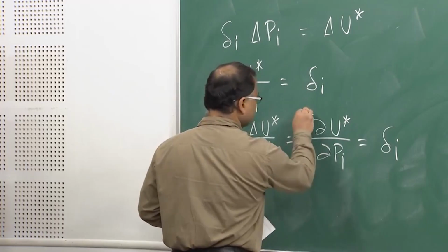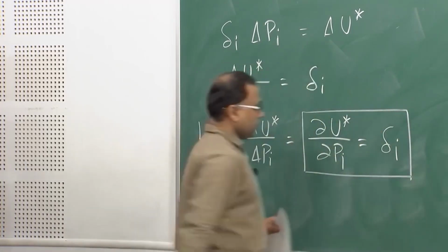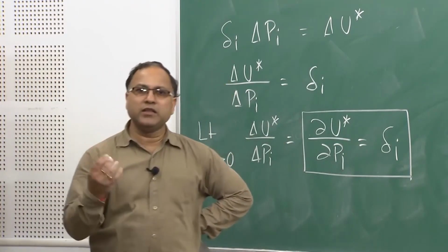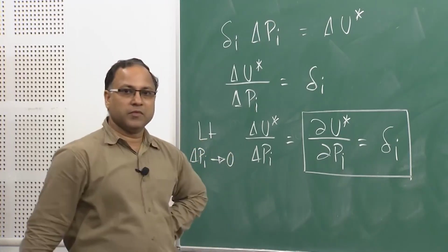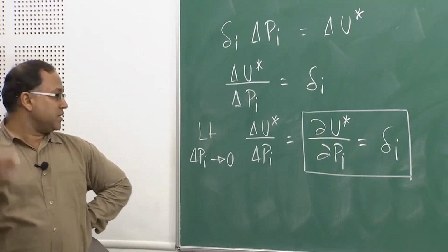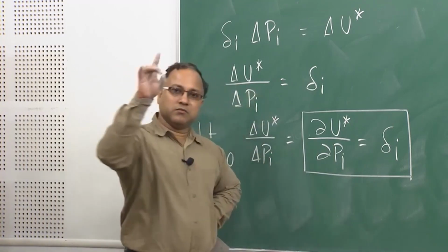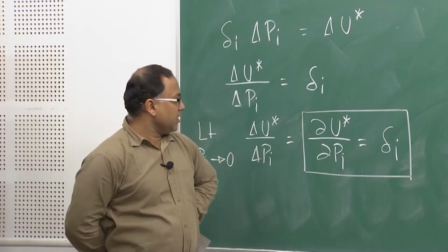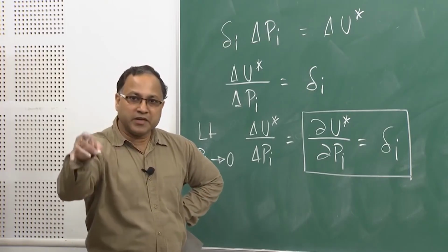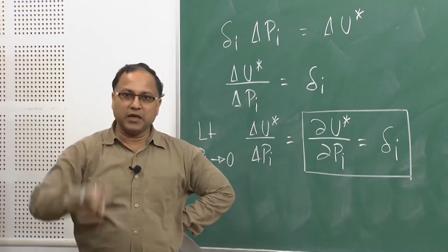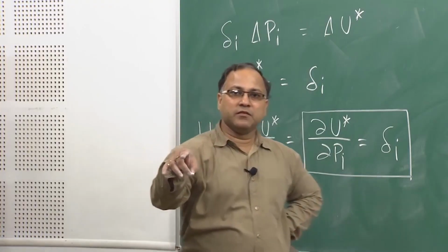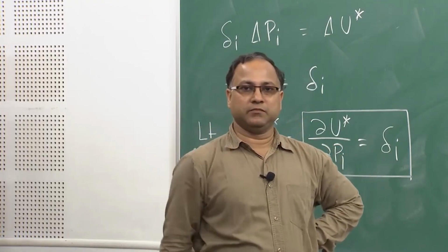You have got an indication that if you manage to calculate the total complementary energy for a conservative system, then if I take the partial derivative of that complementary energy with respect to some force Pi, that partial derivative will give me the deflection along that force Pi, right.